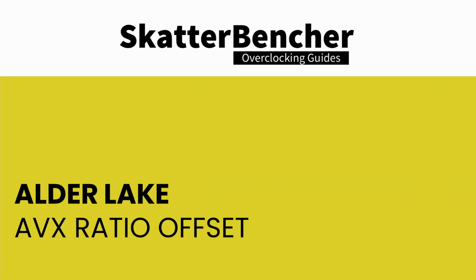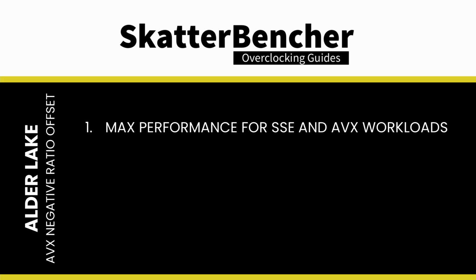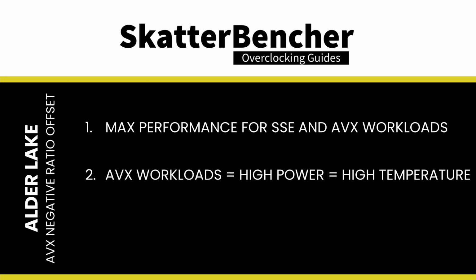Intel first introduced the AVX negative ratio offset on Broadwell-E processors. Successive generations of Intel Core processors inherited this feature and eventually also added the AVX512 negative offset to it. AVX negative ratio offsets are very useful to achieve the maximum performance for both SSE and AVX workloads. Generally speaking, an offset of 2 or 3 is recommended, but it is highly dependent on not only your cooling solution, but also the motherboard you're using. That is because AVX workloads are very demanding and therefore require great cooling and power delivery.